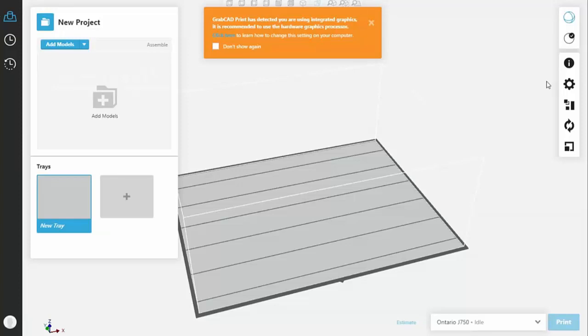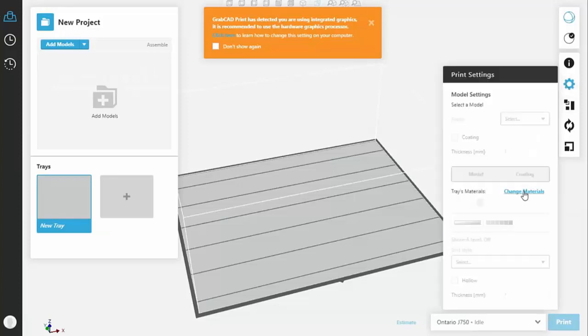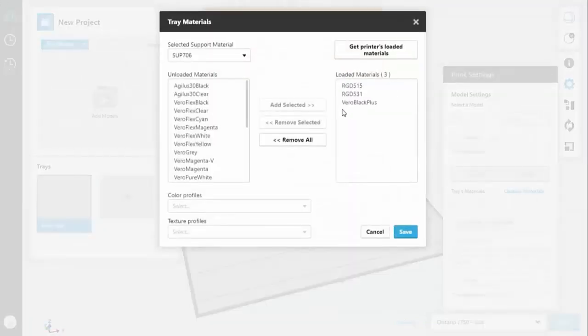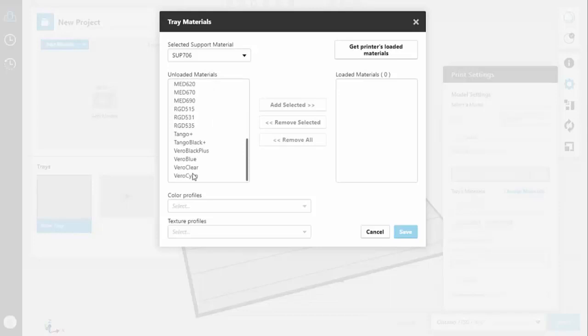The first step in this is to configure our printer. So if we look at the current material I have, the materials loaded are not full color materials and would not enable full color printing. So we want to remove all those, and then generally speaking, the preferred palette for color printing with rigids is cyan, magenta, yellow, black, white, clear. And those will allow us to do pretty much anything we can imagine or design in any of the different software that we're going to be looking at today.